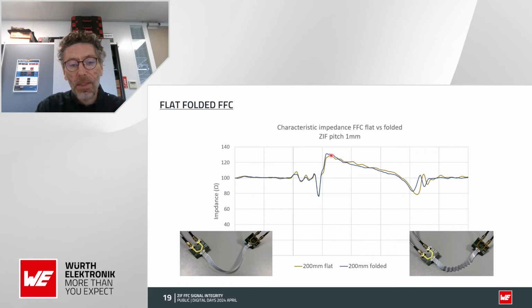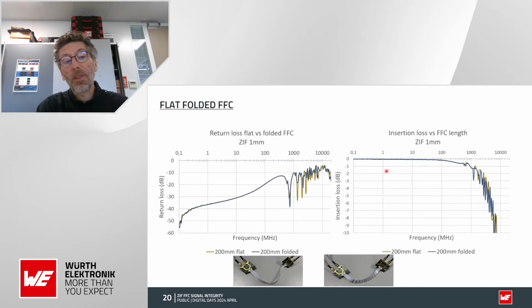Well, not really actually. Flat and folded gives more or less the same impedance. So normally we should not have so much difference in the return loss and insertion loss. And that is what happens. So return loss and insertion loss are more or less the same. So the answer is clearly the flat and the folded does not give any influence on the signal integrity. So do not be scared to use a folded FFC.